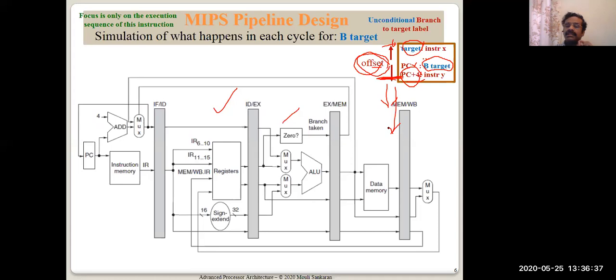Why is the relative address given? Remember one thing, it's a 32-bit processor and the PC, the program counter, is also a 32-bit register, and we are trying to find out the new value of PC. If the instruction should hold the total value of the PC itself, it needs 32 bits of locations. But our instruction itself is 32-bit wide. It is not 64-bit. Either you have to increase the instruction bits or try to accommodate it within the 32-bit value. How can it be done?